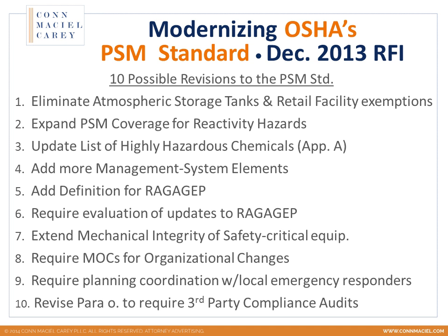Coverage for reactivity hazards. As you know, if you deal with this standard, a number of reactive chemicals are listed in the listed chemicals, but wholesale reactive hazards are not covered. OSHA is asking for comment on whether to cover reactivity chemicals that are reactive wholesale, essentially, in the standard. So expanding the standard considerably to cover reactive chemical hazards.